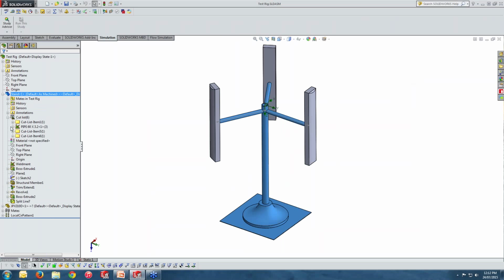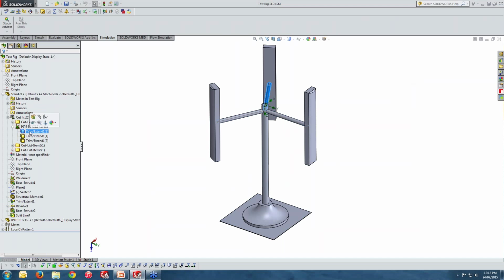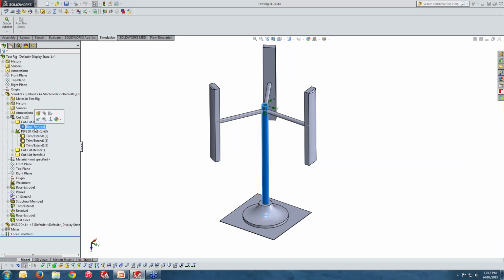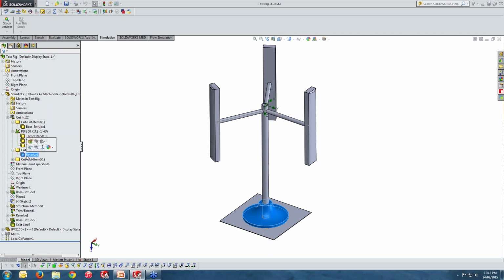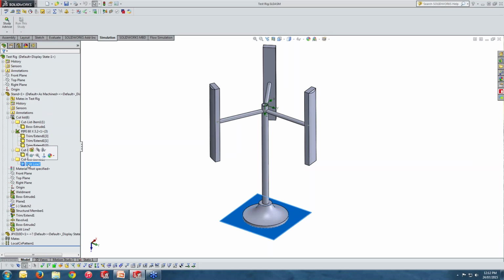We have some beam elements, weld profiles, these three objects, and also some solid objects like this one, and I did it on purpose. Although it is a beam, I haven't created it using our weldment profile, to show you how you can assign a beam even to a solid structure. And we also have more, as this is the solid revolve part, and we do have this shell.